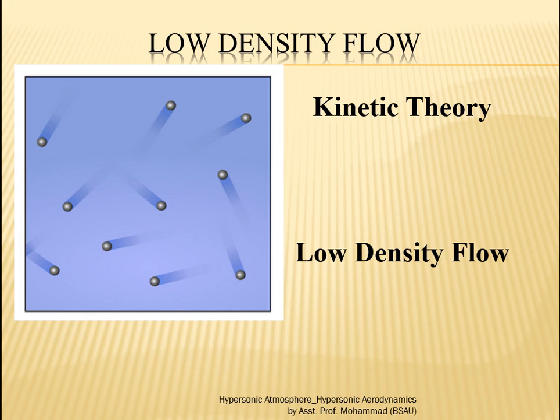In these widely spaced particles of matter, under these conditions, the aerodynamic concepts, equations, and results based upon the assumption of continuum begin to break down, and they are no longer valid, and they don't give realistic values. They just give very ideal values which are no longer applicable. So we start changing our point of view, and we start using concepts from the kinetic theory to analyze and find the aerodynamic behavior of the fluid. And this regime of aerodynamics is called low density flow.